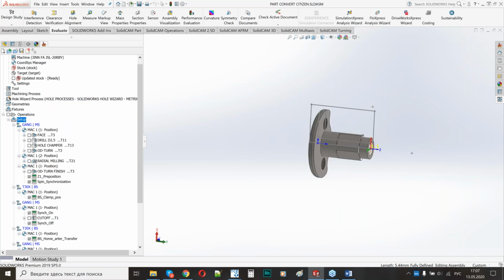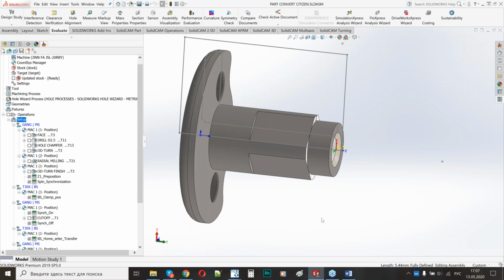So this is it. Today I showed you advanced operations. Of course, advanced operations depend on the machine itself, on the facilities of the machine. There is a long list of advanced operations that we have depending on the machine. I showed you today a very common operation, for example, the long drill and synchronized movement, superimposition in V1, V2. It is very common. The superimposition with the axis, each Swiss type machine has it, and it is included in the transfer sequence.